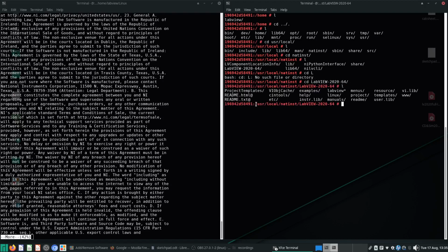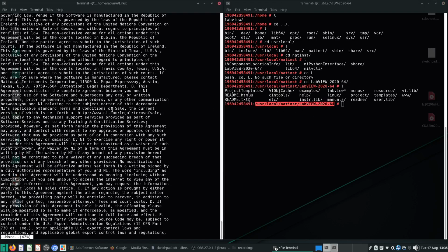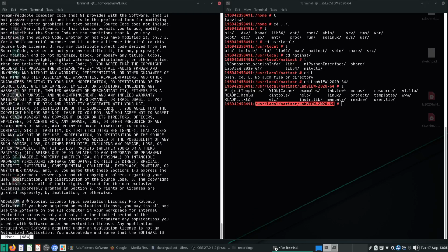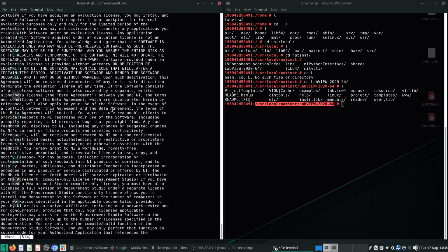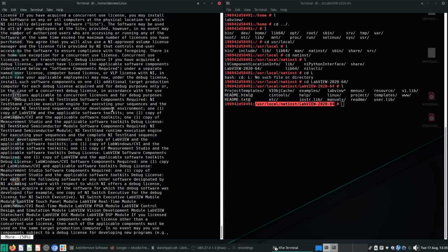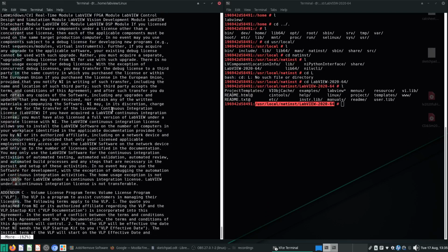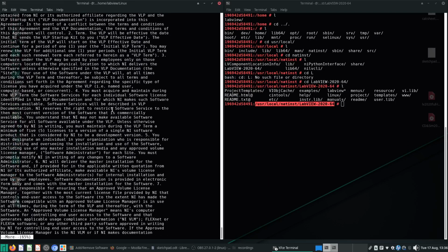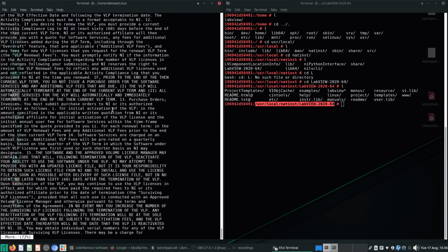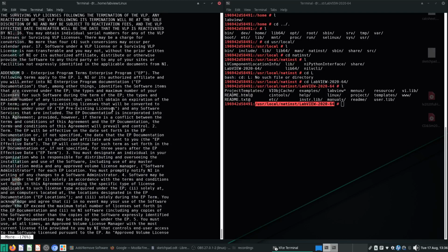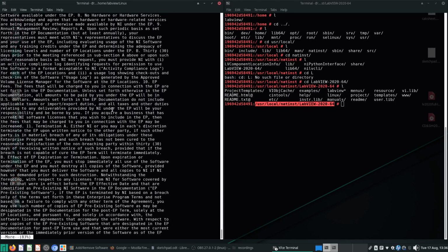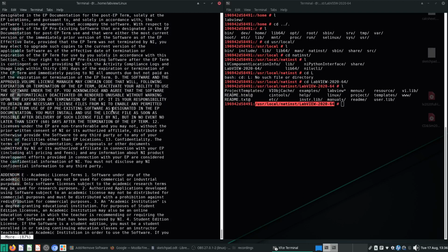This is the file path I want to use, which I will just copy and paste it up. So remember, we want to install it in this specific folder, user local national instruments, labview 2020-64. Of course, we can adjust the install script to install what we want, but let's see whether using some of these default installers is going to help us at all. Okay.